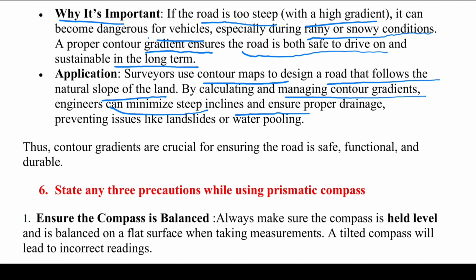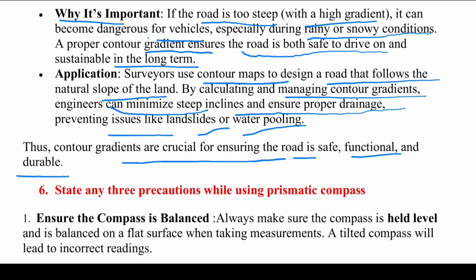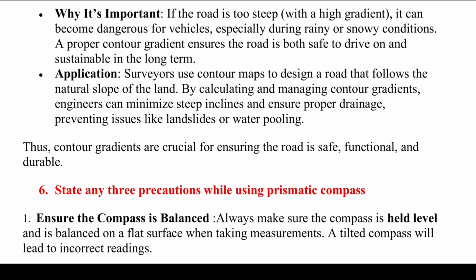Okay, we have to ensure we provide a proper drainage system to prevent landslides and water pooling. So contour gradient is crucial for ensuring road safety, functionality and durability. That also we have to see in the construction of the road.